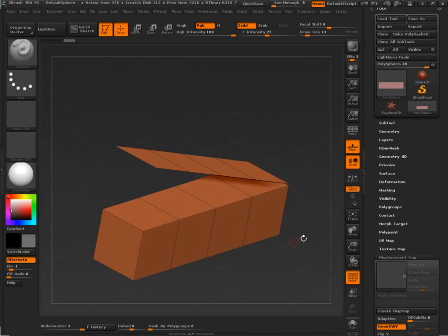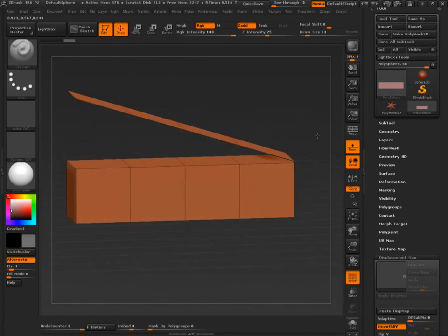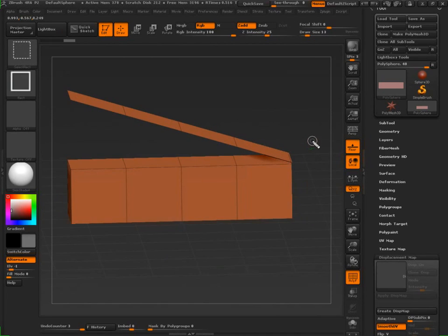This little device, simple polygon model, is what I have seen companies use to kind of calibrate displacement maps. What we do is we divide this and we put a little bump that touches the top, a bump that touches, and a bump that touches. And then we use this to kind of help us understand what our settings need to be inside of Maya Mental Ray to kind of get the accurate readings.